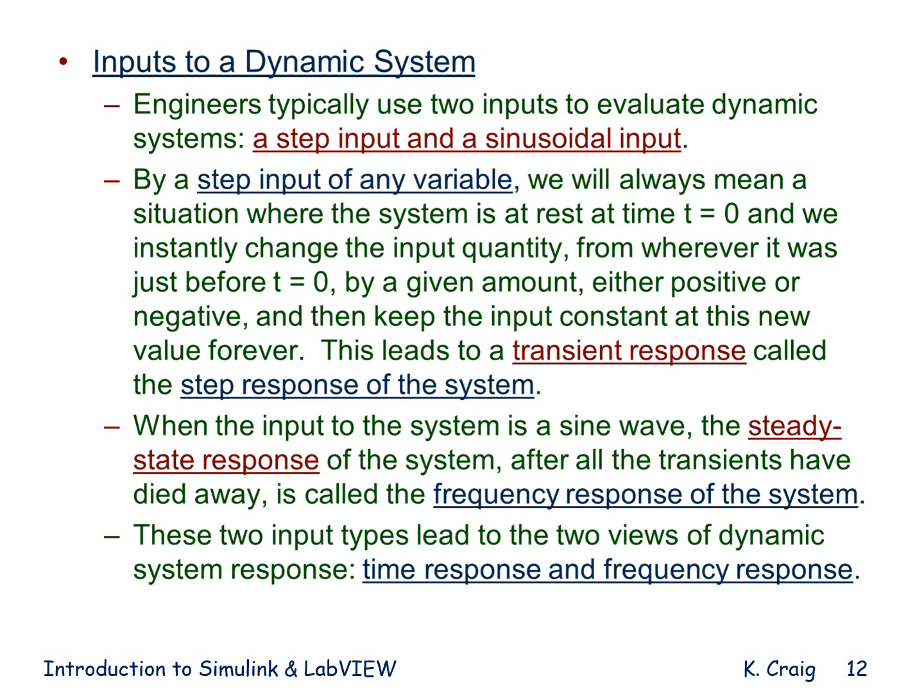This leads to a transient response called the step response of the system. When the input to the system is a sine wave, the steady state response of the system, that is, after all the transients have died away, is called the frequency response of the system. These two input types lead to the two views of dynamic system response, time response and frequency response.